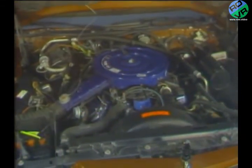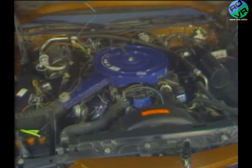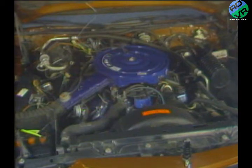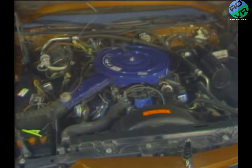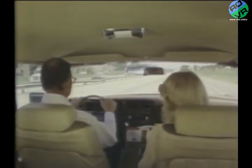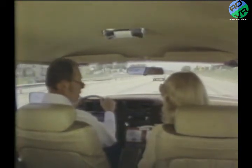Our final area related to NVH problems involves the engine and accessories. Vibration in this area can be diagnosed rather easily because they do not usually vary with road speed. Of course, road testing is necessary to isolate the specific engine or accessory NVH problem. Engine and accessory noise can sometimes worsen with increased engine speed. While road testing, run the vehicle at various road speeds to note the objectionable noise.